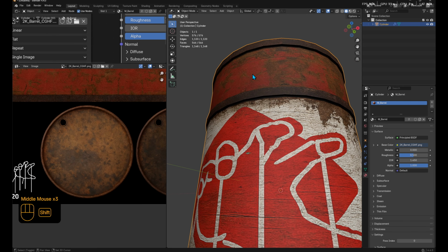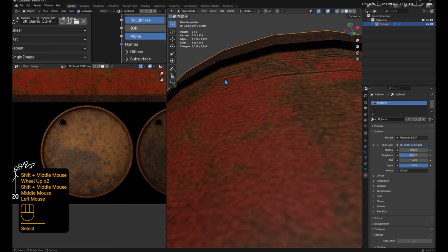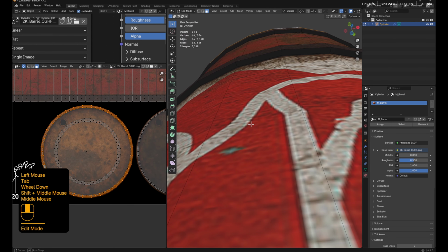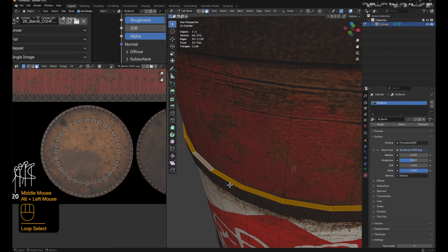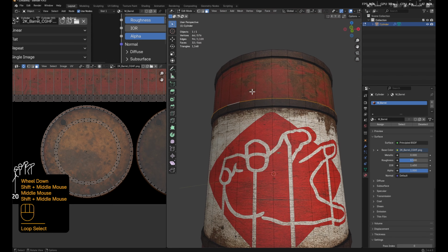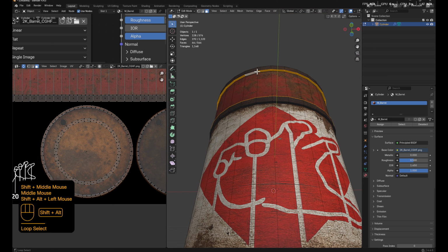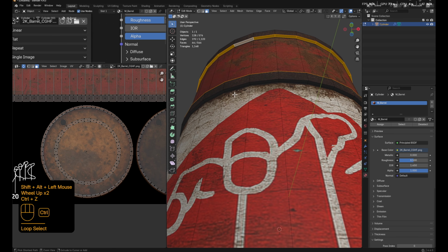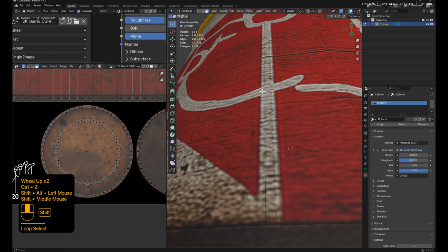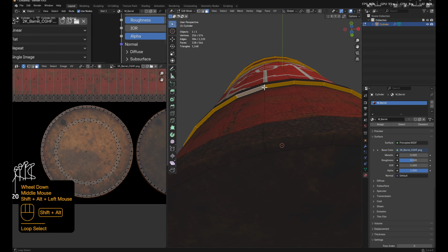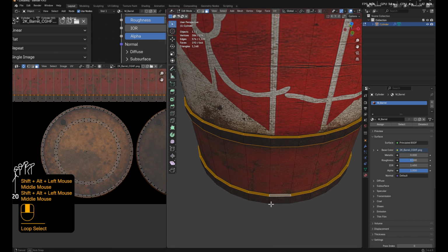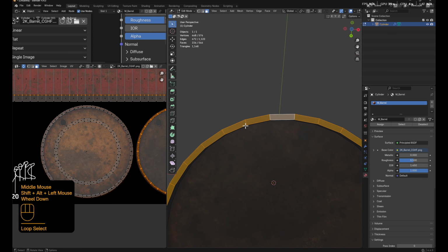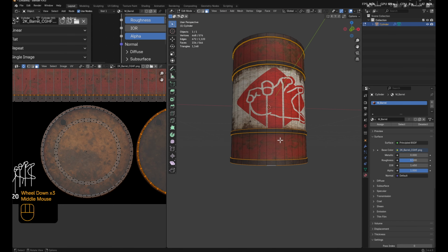So now I just want to go and check all my model and find whether we've got some stretching. These darker areas, I think we can get away with it a little bit, but there is some stretching there. So what we'll do, we know that we extruded, so we'll select all of these by pressing Shift, Alt, and left mouse button click. Undo. That one, that's what we want. That one, that one, that one. We'll even do that one. We'll save that inside one for later.